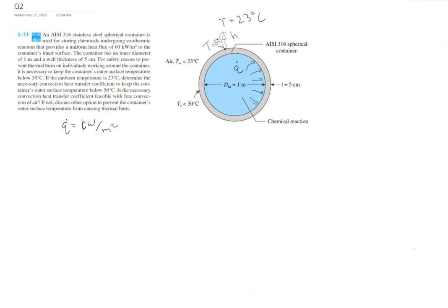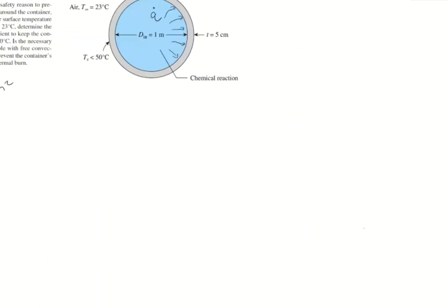So for conduction, it's k, and for convection, it's h. But h is actually a little more complicated than k. k is a property of the material. h is a property much more of the conditions. So the fact that it's air is going to be one of the things that factor into h, but also maybe how much wind there is, and the way in which the air is interacting with the surface also matters. And so that's why you'll see stuff like fans in your computer, because that's going to increase this coefficient. So for the first little bit of the course, this is going to be given, but later we're going to understand how that's calculated.